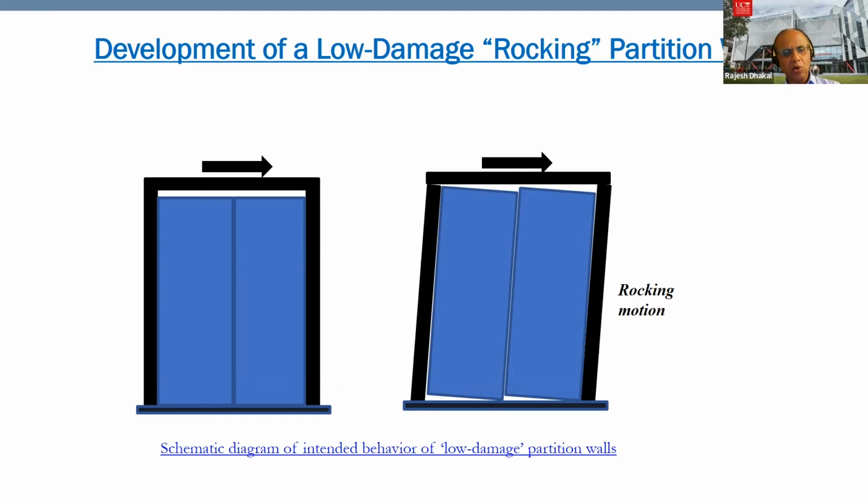So that required quite expensive and extensive sealant application to fill those gaps to get limited drift capacity. But in this project, our idea was to avoid those wide gaps in the vertical element and provide them at the top, which is hidden naturally by the top track. So you don't need to fill those with sealant because the track will cover that anyway, right?